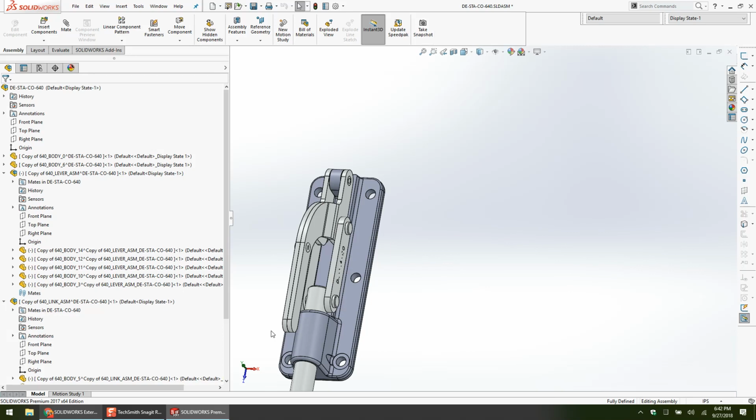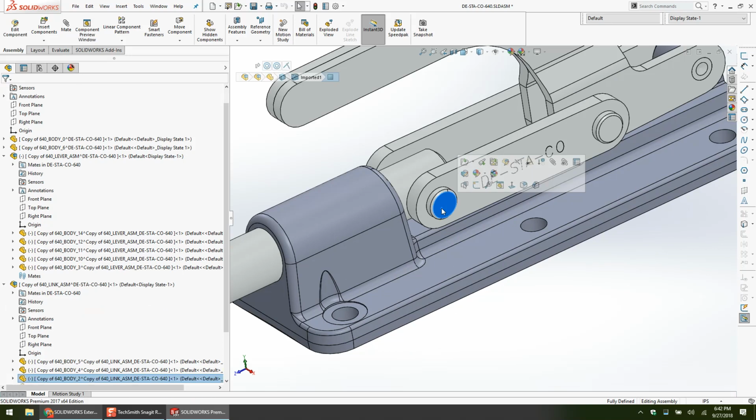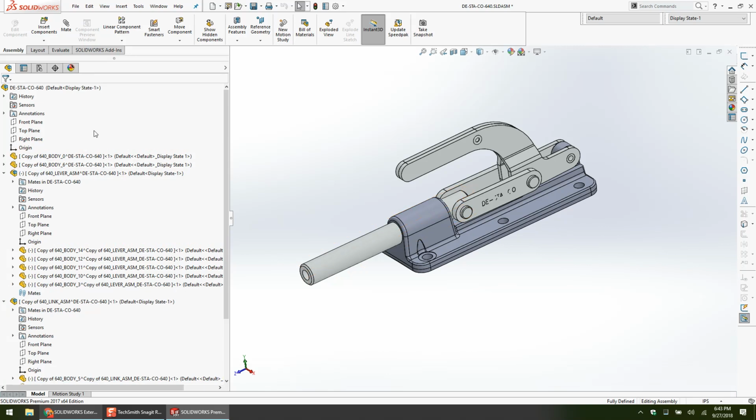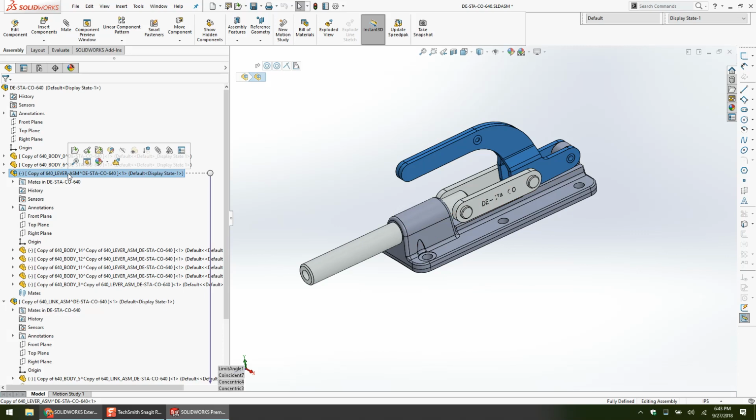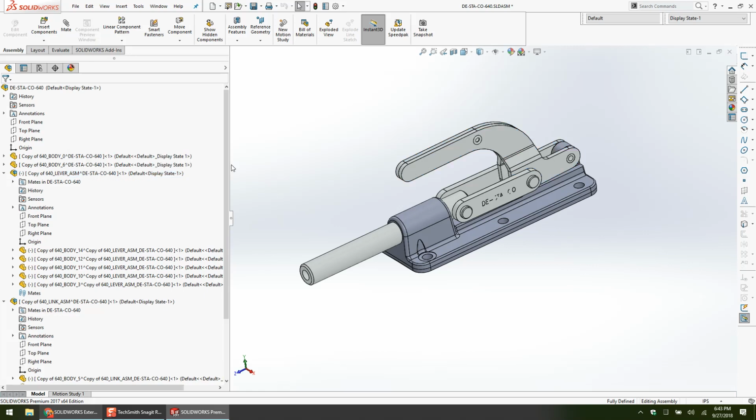The other thing that it does is, when I download this Stego clamp, this pin in Stego clamp's world is the same pin as the pin used in a different size. Well, now I have a file conflict because I have the same physical file in a different folder on my server or on my PDM or whatever it might be. If I virtualize everything, the only file in my PDM or on my server is this assembly file. Every single one of these subfiles can have the identical name as the other Stego clamp that's one size smaller or one size bigger, and I have zero conflicts.